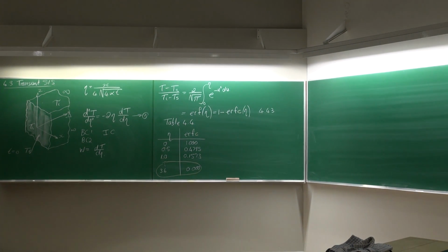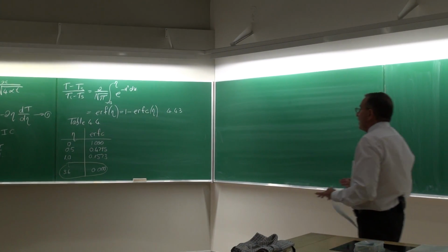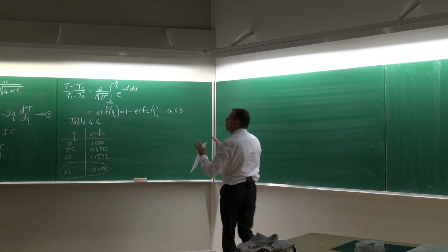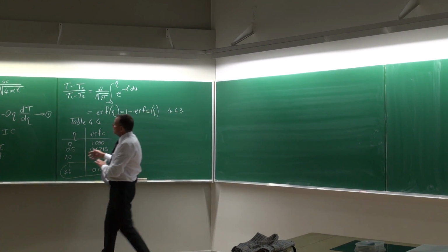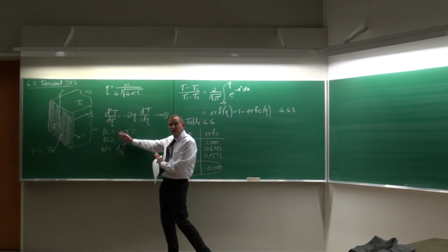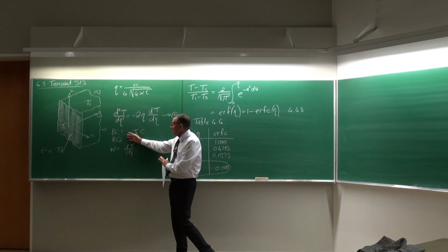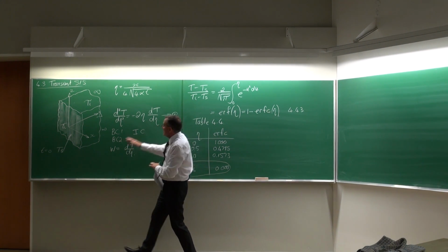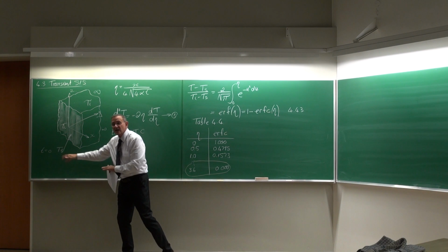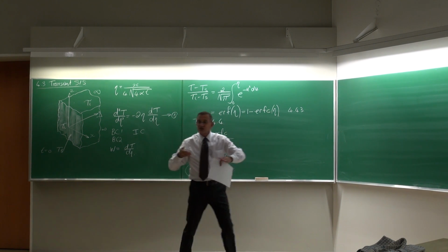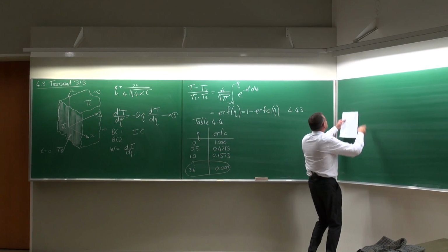Okay. So in general, there are 4 different types of solutions which can be generated by using different boundary conditions. So this is the boundary condition, the solution, where at T equals 0, the temperature on the surface changes to Ts.